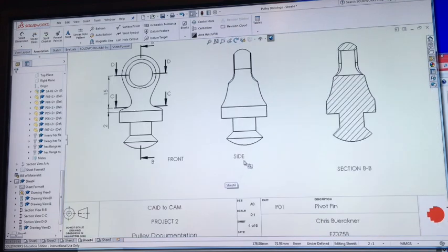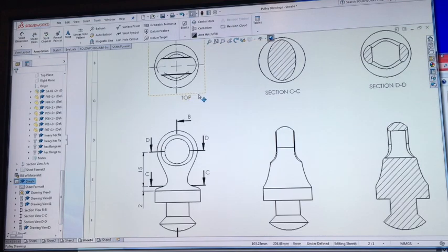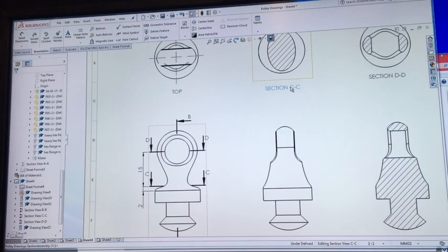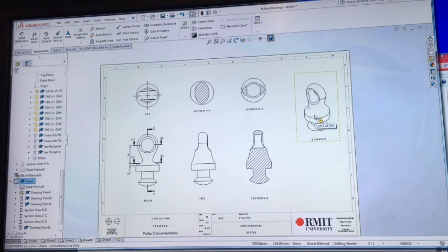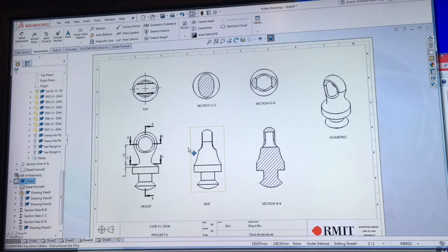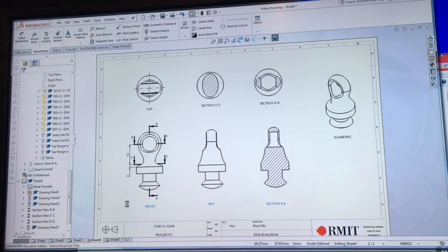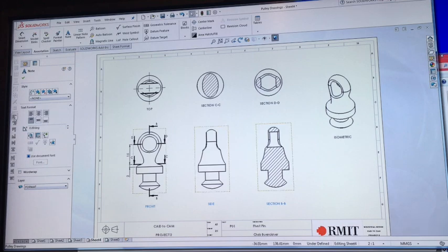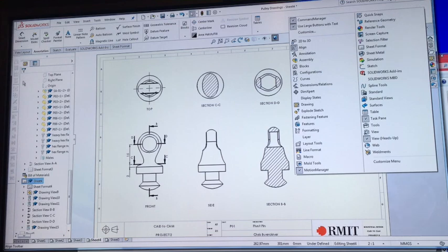Once you've dropped that text, you can then select it and reposition it. So one of the things we'll be going for with our drawings is consistency. So on every page, we typically want to have our view labels in the same position, relative to their drawing views. If you want to get very pedantic about it, you can select text and you can align it. Right, but I'm not too fussed about that. So that's using the align toolbar, which I've popped up on the side here.